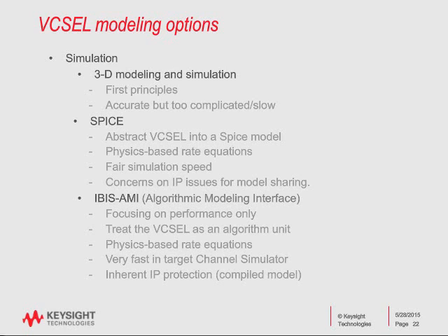So what other options do we have? Well, we could create a SPICE type model, and one option would be to use physics-based rate equations, and that's good. You end up with a fair simulation speed because it's in SPICE, but again, there may be concerns here about IP issues for model sharing and those kinds of things.